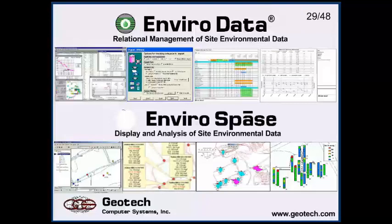You hit it with the hammer with a certain number of psi, certain number of blows per minute. They call it the blow count. And then you see how far it penetrates. So the harder you hit it and the more times you hit it, you figure out how far down it goes. And it basically tells you the penetrability of the material, but if you've got an idea what the material is, which you would for the soil boring, you can use that to calculate things like the bulk density. And it's used a lot in engineering work because if you're going to put a bridge there, you want to know how it's going to compress when they drive semis over it.